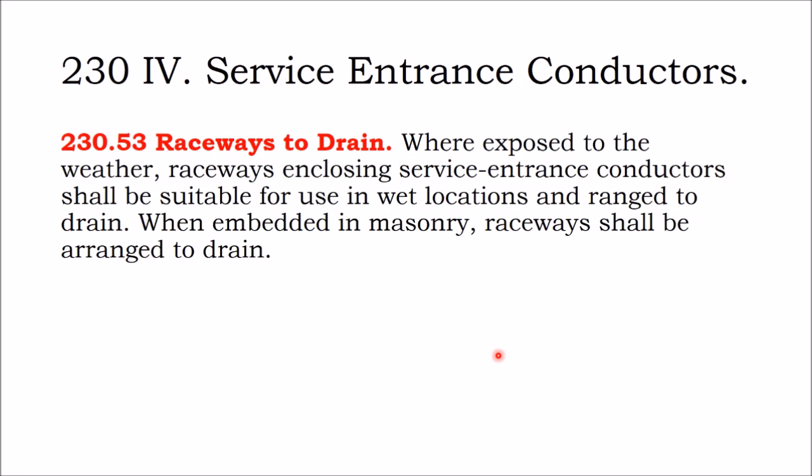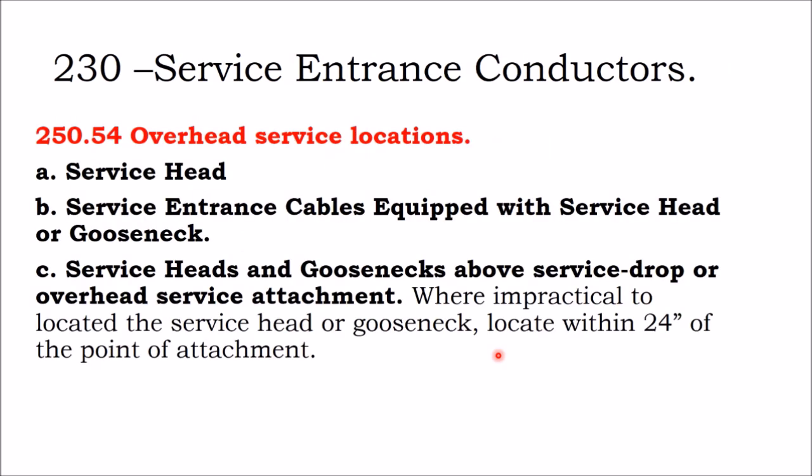Raceways to drain. Where exposed to the weather, raceways enclosing service entrance conductors shall be suitable for use in wet locations and be arranged to drain. When embedded in masonry, raceways shall be arranged to drain. So if you're burying conduit in concrete, don't have the conduit on such an angle that it will fill up with water if water gets into it.